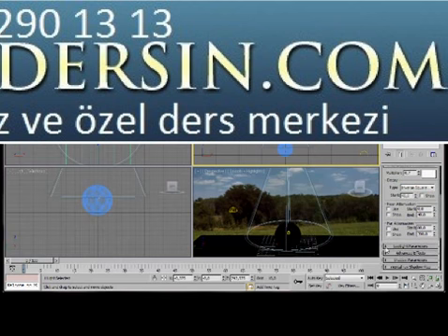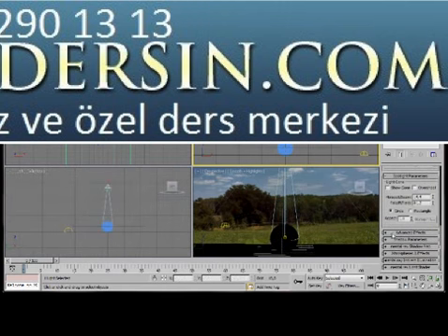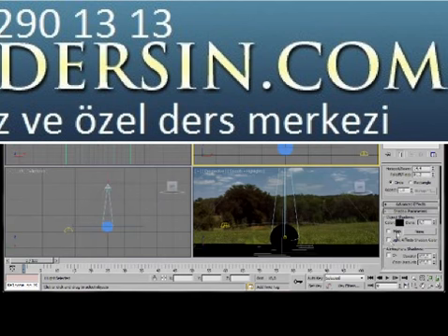Now we'll just toggle down. Under spotlight parameters, the hotspot beam, we're going to bring it down, right down. If you notice in the perspective viewport, the inner circle of our spotlight is getting smaller. There we are. We want it just to the width or the radius of our ball. Now the fall off field, we can bring that one up. We can stretch it right out to the end of our plane. Let's scroll down to shadow parameters. Under object shadows density, let's insert 0.8.